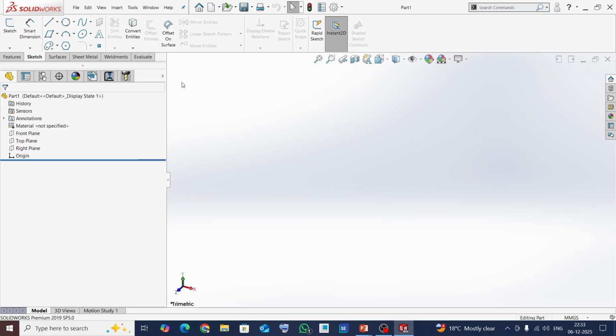These are the quick access toolbars with the Pathfinder. And suppose we have used some commands to create a part, that will show here. So this is the Pathfinder or individual part tree. In this individual part tree, we can see the sequences or operations done on the part to create it.